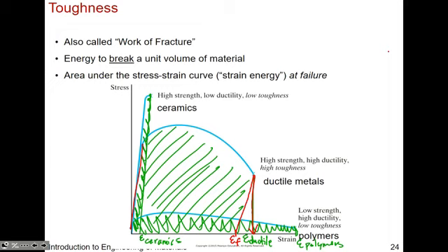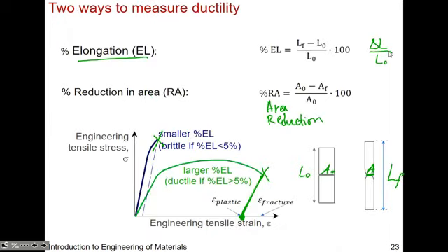I'm sorry to clarify this, but could you clarify exactly what ductility means again? Yes. Ductility is just basically the strain, right? To measure it, you're comparing strains. So you're saying that a material is ductile or more ductile than something else if the strain at the point right before failure is higher or lower than another material.